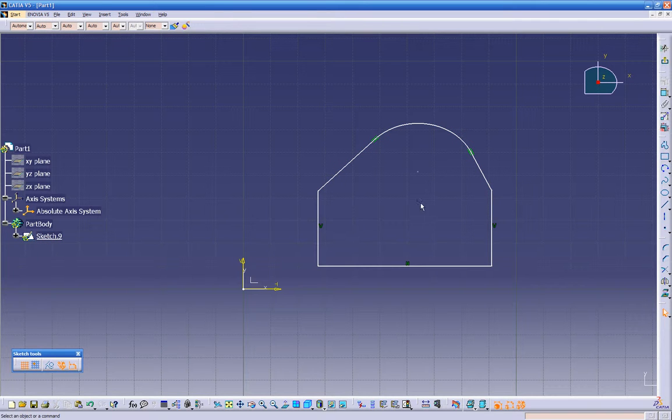And let's give it some dimensions again. So you know it's a vertical line right here, a horizontal, sorry. H is for the horizontal and V for vertical. So it knows that this line and this line are vertical. So let's give it some dimensions. Let's go to the constraint again. Click on this line with this line. Let's give it a dimension.